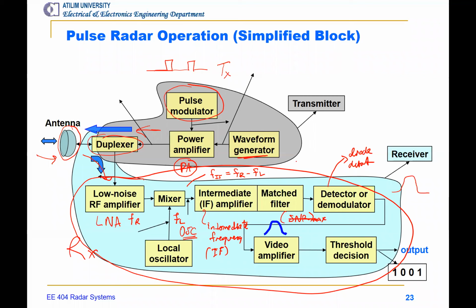Before, we had a cosinusoid, while here we remove the cosinusoid and take the envelope only. So the waveform that we showed in the first slide is just a rectangle, but not a perfect rectangle. That's a distorted rectangle, but there is no cosine inside. We then have an amplifier, typically to amplify the signal, and then make a decision by threshold.